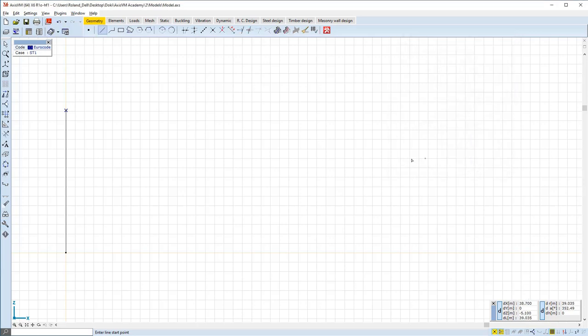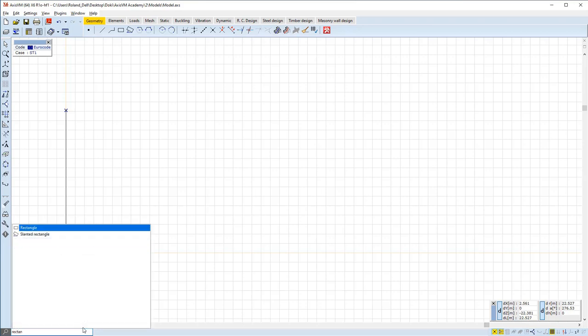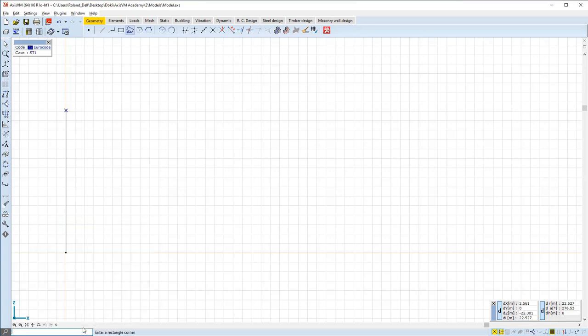The second option to start a CAD function is by searching it through the so-called Smart Search and Command line, which is placed in the bottom left corner of the screen. The search line will offer the best match and the desired function can be started by pressing Enter. This search tool can be particularly useful for newcomers, as they may not know where the button of a function is placed on the user interface. Still, they can find it by searching for the action they want to perform. The command line has further areas of usages as well, which we will cover later.